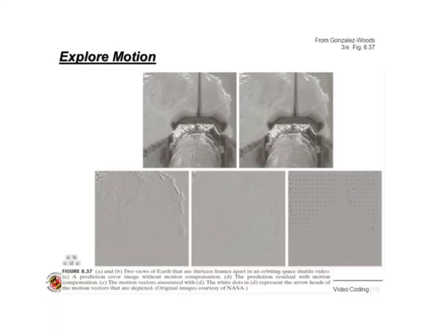To generate this prediction residual, we divided figure B into non-overlapping 16 by 16 macroblocks and compared each macroblock against every 16 by 16 region in figure A. The reference frame search fell within plus or minus 16 pixels of the macroblock position in B. The resulting displacements are the x and y components of the motion vector, as shown in figure E. The white dots in the figure are the heads of the motion vectors. They indicate the upper left hand corner of the coded macroblocks.